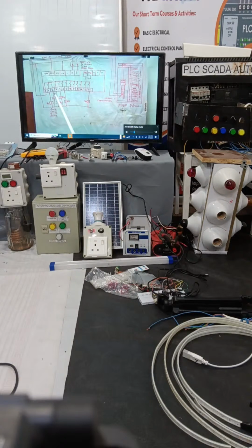This contact will not get damaged, and this contact will energize the main, big power contactors. This is called capacitor duty contactors, because there are many types of contactors, such as lighting contactors and motor switching contactors, but this is a special type, so it is called CDC or capacitor duty contactor. Now in the next topic we will see the use of reactors, detuned reactors.